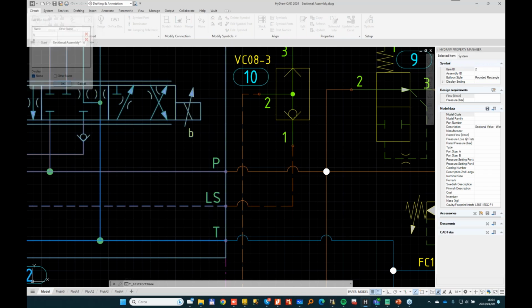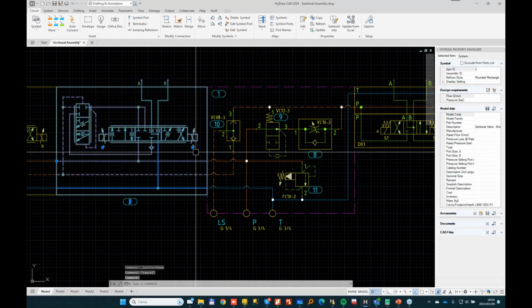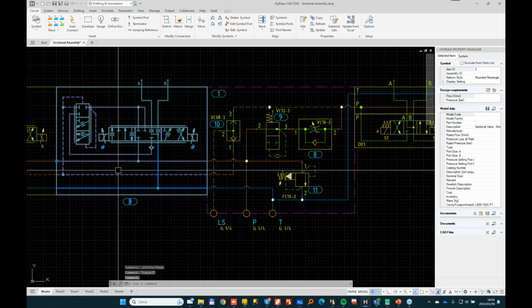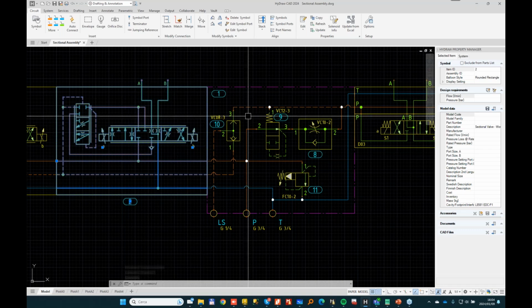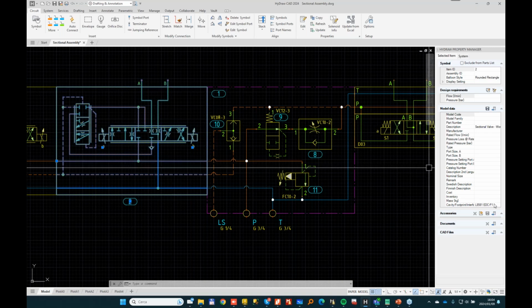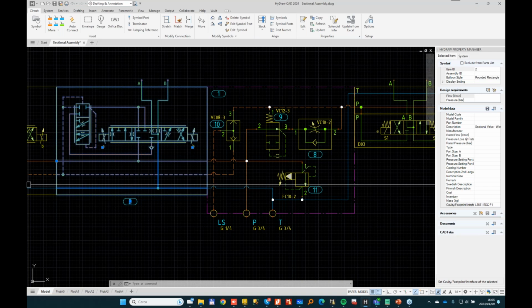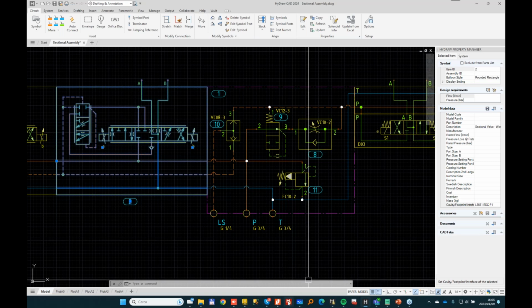In order to have an efficient export to MDTools from Hydro, in this case, we consider this element as really an interface fitted to the block. So this element in the Hydro Property Manager will need to have a cavity name. I put the name L8581 EDCP1, which is the element that I'm using on the left. And this cavity name corresponds to a footprint I have made in my MDTools library.